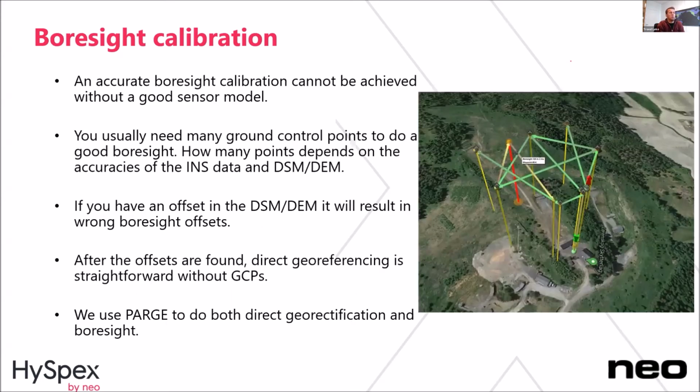To do a boresight, it's the same for airborne and UAV. We fly across. This here is a shooting range that we fly every week when we're delivering UAV systems. We have a lot of GCPs on the ground, and we fly across over those GCPs, flying each of the flight lines in this crosshair in both directions. So we get 4 flight lines in all the boresight flights.